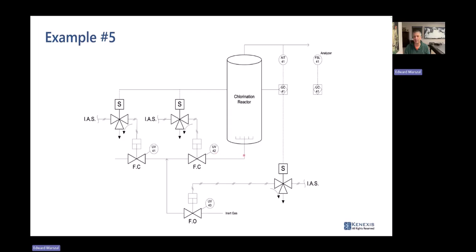So you need to do your risk analysis, and what the reality of this analysis showed is that there are other situations, specifically if you shut down your vaporizer, that's also going to trigger a reverse flow in this situation. And that is its own safety instrumented function that is going to be detected by a low differential pressure there. So yeah, you got to go cause by cause through the risk analysis process. And in many cases, you will see that the secondary safety function by itself is not enough.